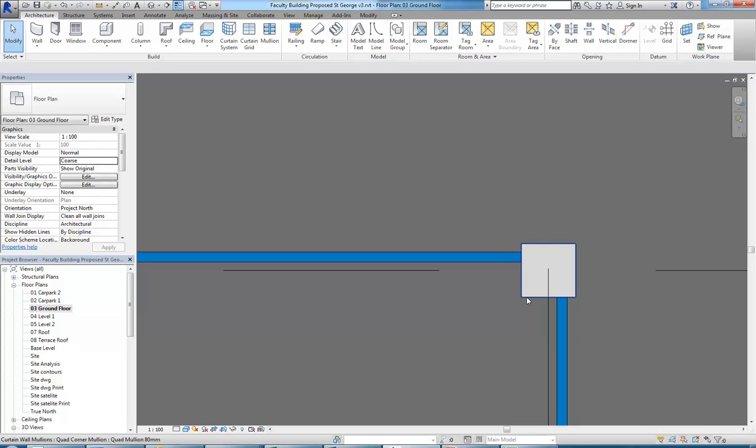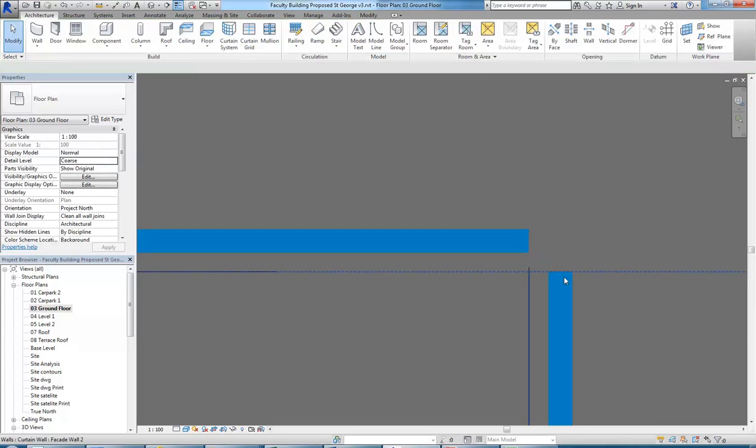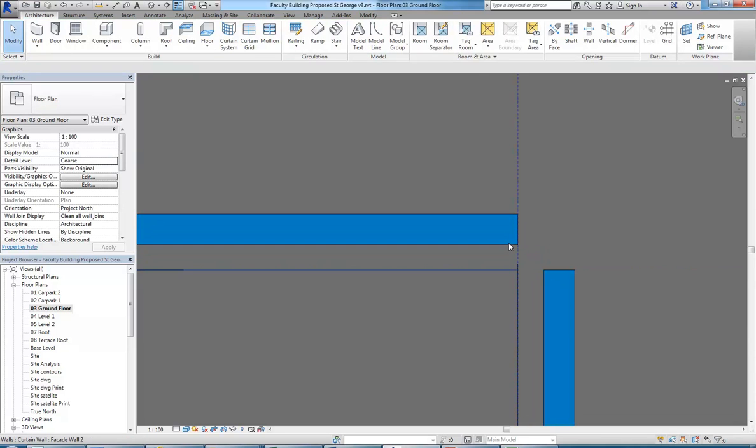You can either do mechanical systems that have suspended glass, but if you've got a frame at the top and the bottom, so you just have a top plate at the top and bottom, that can be recessed, and then you can just have silicon joints in between the glass. And that gives the appearance of frameless. But the problem then with a curtain wall is that if we delete this, you'll have a gap there where they join at the corner.